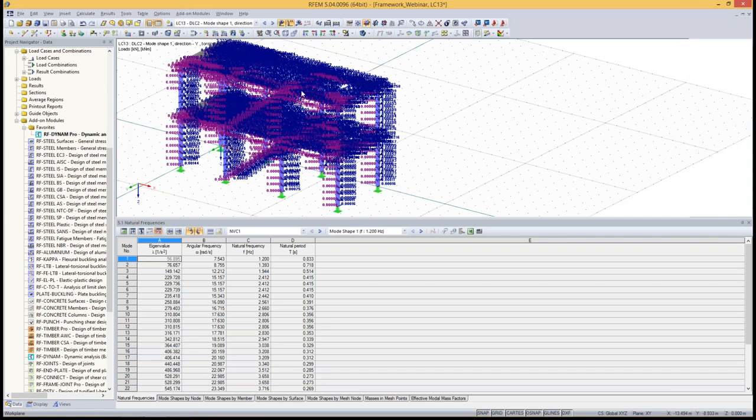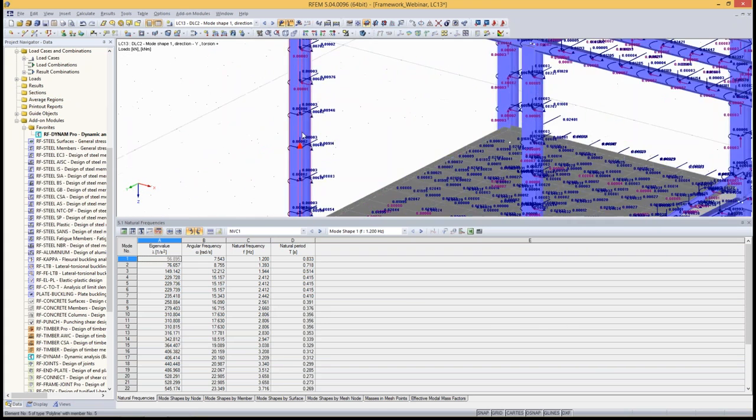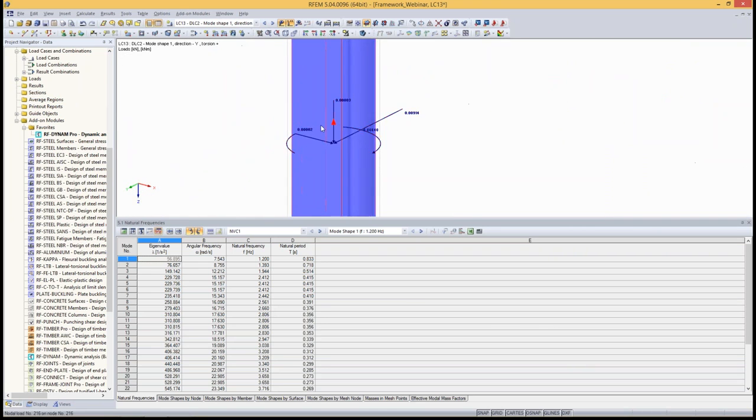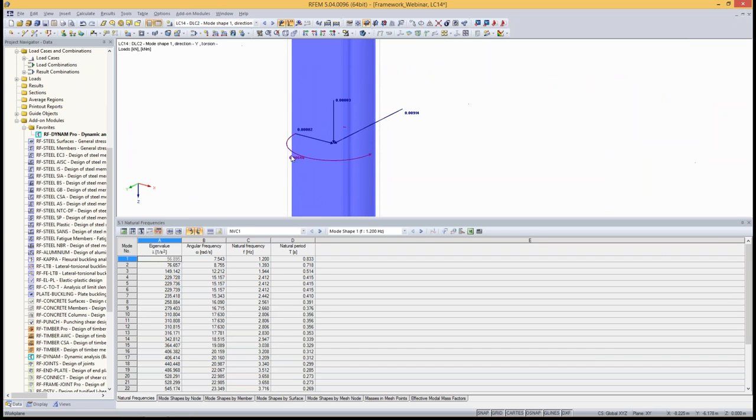And let's just have a look to it. It looks terrible if you don't zoom in. You have so many loads, but if you zoom in, you see the applied equivalent loads in all 3 directions, and you see the torsional moment. And this is the torsion plus case. And if I switch to the other case, the only thing that changes is the direction of the torsional moment. So the number stays the same and the equivalent loads stay the same as well.